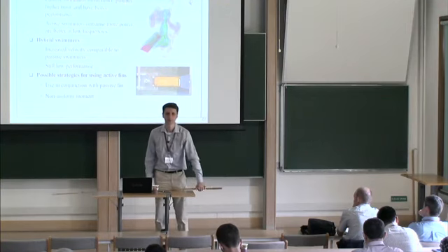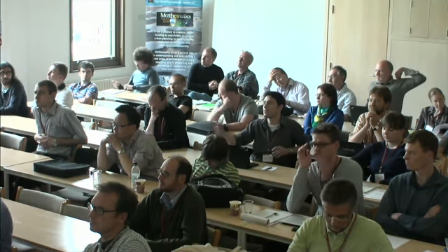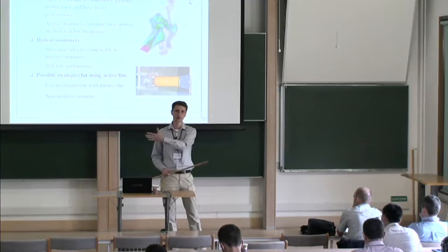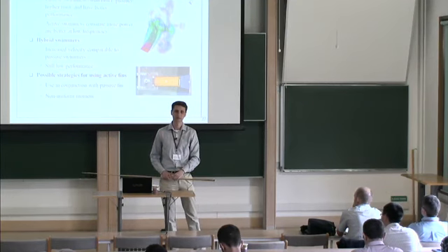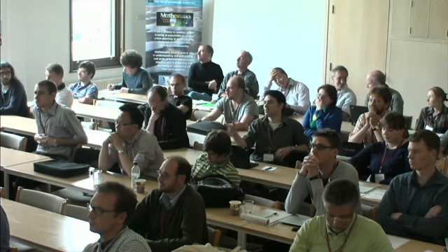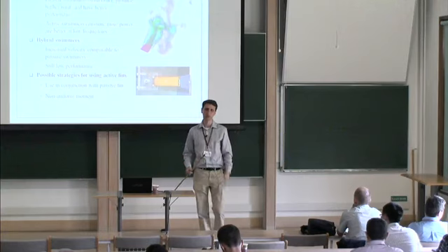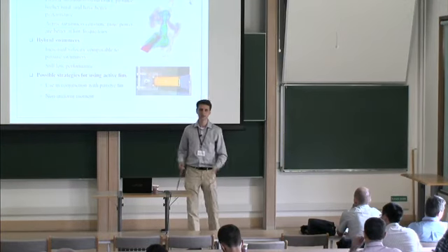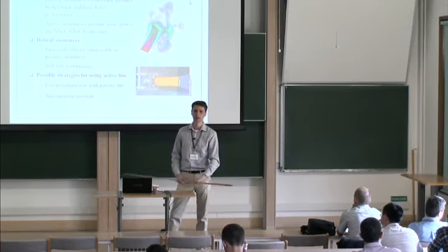Well, you can have symmetry breaking in the fluid, which will lead to lateral forces. We impose the boundary, so we don't have it. Oh, you mean is it stable or not, if it tries to swim aside? Even with symmetric lateral motions of the fin, even if the kinematics are prescribed and symmetric, you can still have symmetry breaking in the fluid, which will lead to lateral forces through vortex interactions. No, what we saw is pretty much symmetrical. We didn't see any difference.